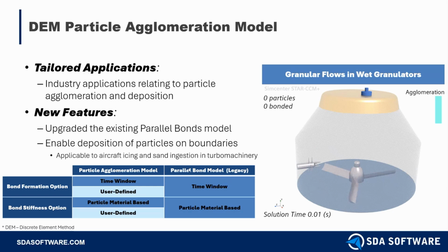Also to be noted, this new model also bonds with boundaries. So now DEM particles are able to bond with walls or airfoil surfaces. This enables applications like aircraft icing or sand ingestion in turbomachinery.